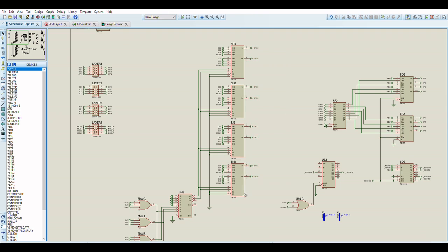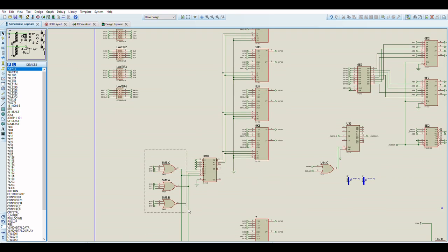The reason we have 3 tests here is because if all of the pixels are transparent, then by default we output the last layer, which in this case is the background color, but it might also be a tile screen, it might be a sprite screen, it might be whatever we decide to plug into the 4th layer.